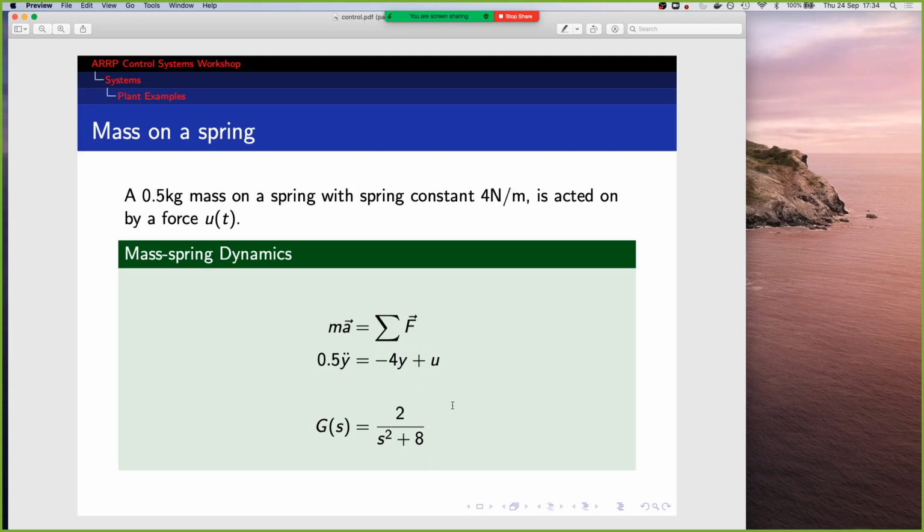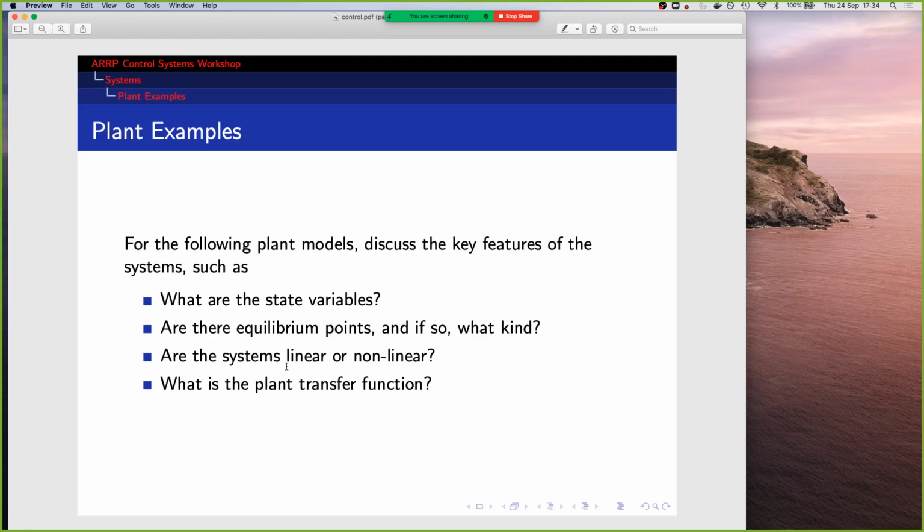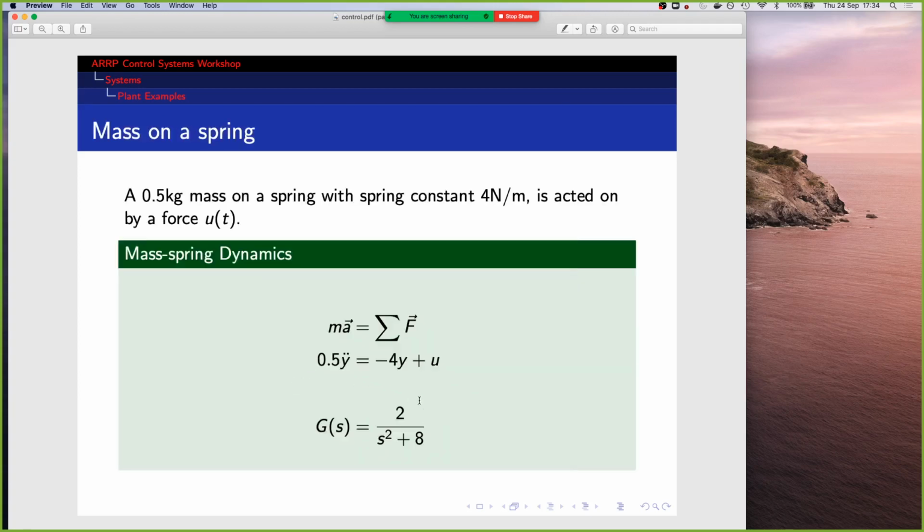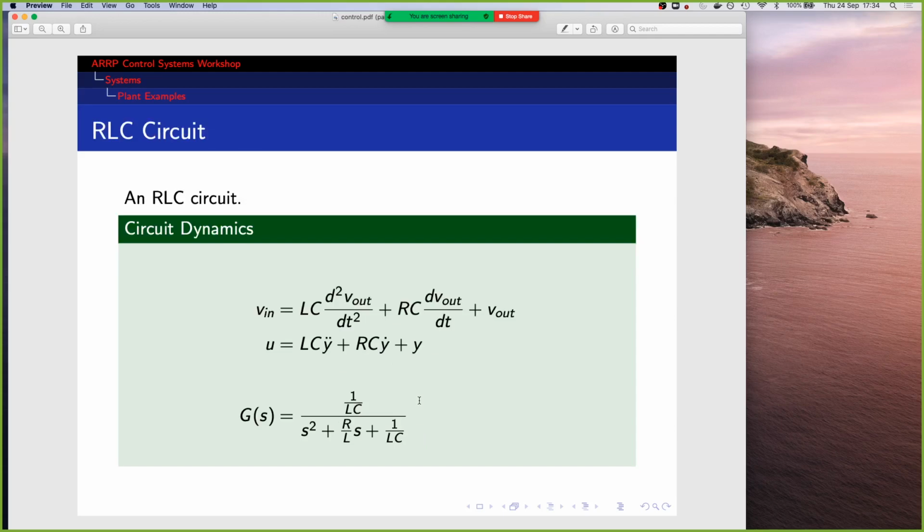And you would be able to see that from this as well. So that can be a little bit of a shortcut. There's a little bit of finesse around that, but often with steady state behavior, if you set s's to 0, you can typically recover some information about steady state behavior from the transfer function. Good. What else did I say? Linear system? I think so. Yeah. So we didn't see any mixing of variables and no odd sine or cosine terms or things like that. Great.